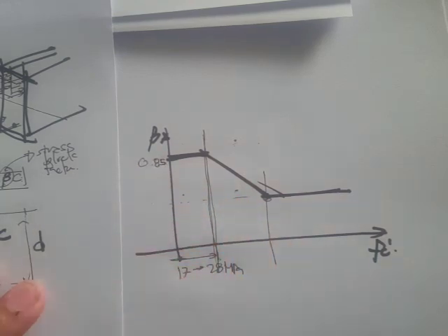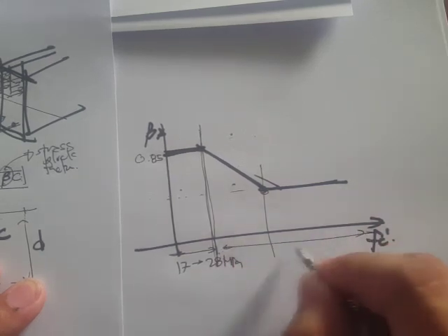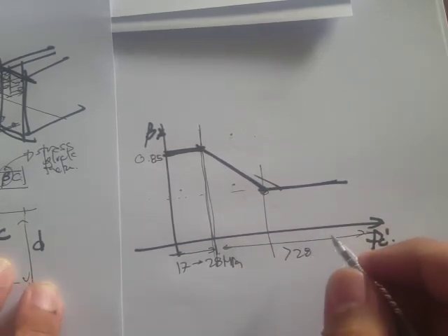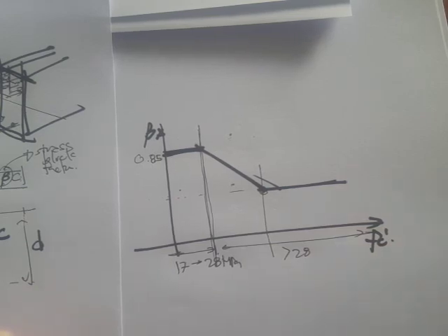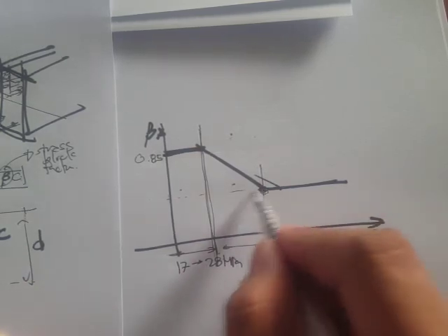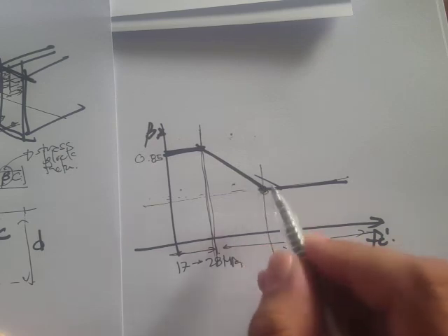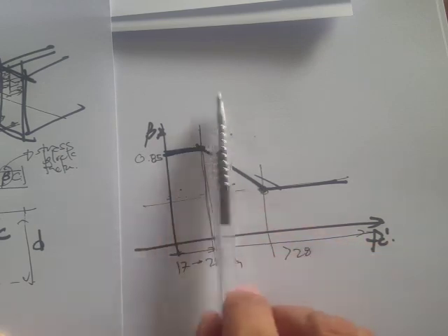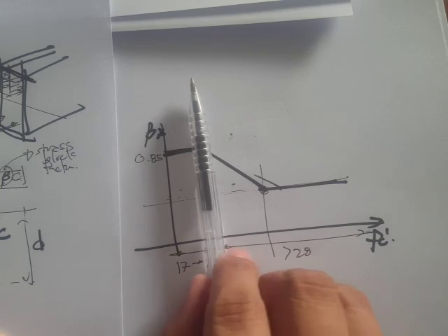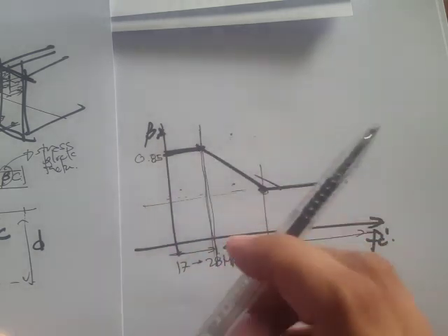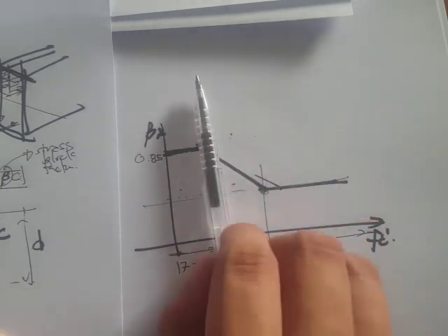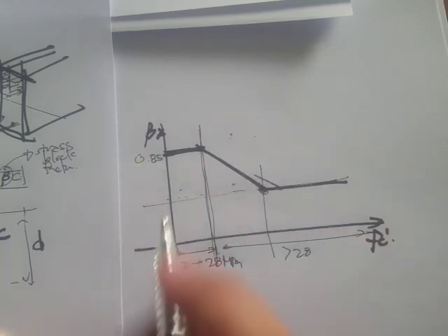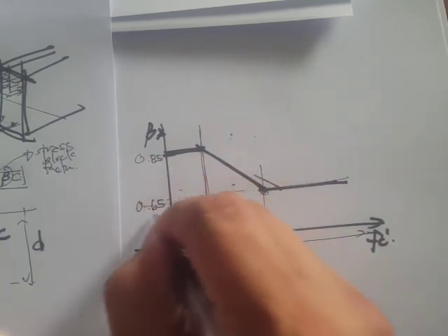then our stress block factor would be 0.85. Now, if we have greater than 28, from here onwards, we have a limiting value. It's actually a range of values from this point onwards up to here, but once we compute and it gets to this lower limit, then we have a value of 0.65.